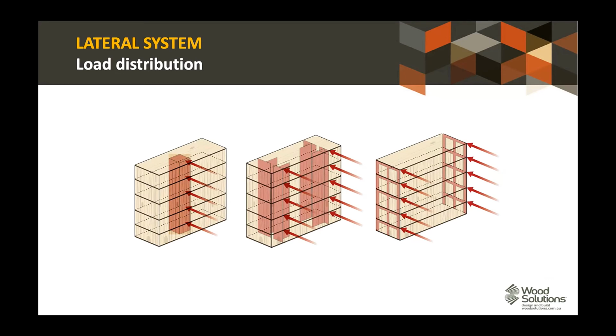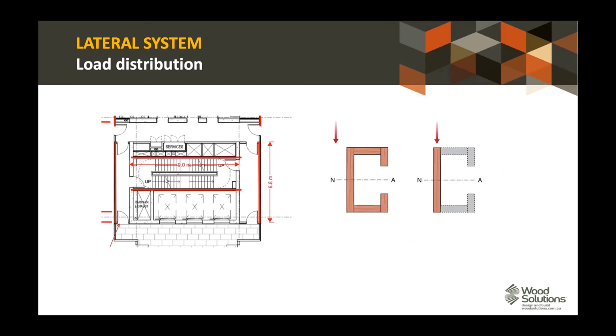So we're in the middle here. We're not looking at a core on the left. We're not looking at a moment frame on the right. We're looking at a provision of walls here. And actually, to ram that point home, even where we have something that might resemble a core, such as the element on the left, we're still really looking at a collection of walls. We're not saying, when it comes to the timber frame solution, that we can build and fabricate boxes or compound elements of cores. We're looking at discrete walls, each of which works in one of the orthogonal directions.